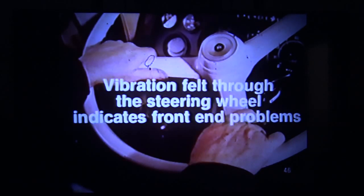If the disturbance is felt through the steering wheel, thoroughly inspect the front suspension, steering gear, and steering linkage. Then check the wheel ends and bearings. One quick check is to preload the front wheel bearings to 15 pounds torque with a dial reading torque wrench. Slowly rotate the wheel while maintaining wrench loading and observe the dial indicator. If there is bearing surface damage, the indicator will jump sharply. If this test is not possible, the bearing assembly should be removed and visually inspected for abnormal wear or damage. Remember to road test after any front-end repairs are made.